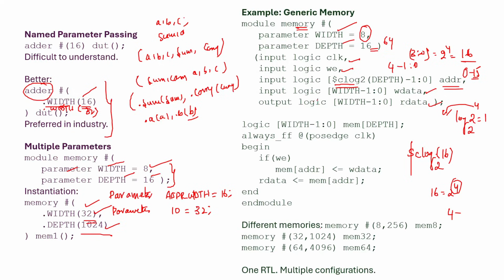Write data is the input, read data is the output. Okay. Now I'm writing the reference memory. In this way, we will consider the reference memory. In scoreboard, sometimes we will take the reference memory. That reference memory stores the expected values, and then the actual memory will store the actual values. Then I will compare the actual values and expected values. If they are equal, it means my scoreboard is passed and then my testbench is also passed.